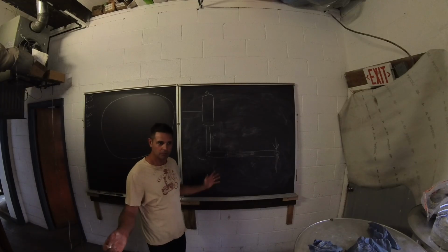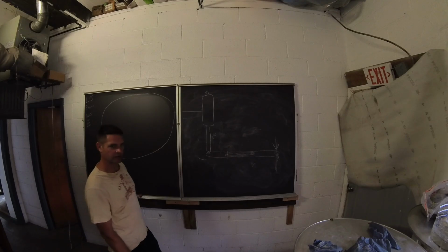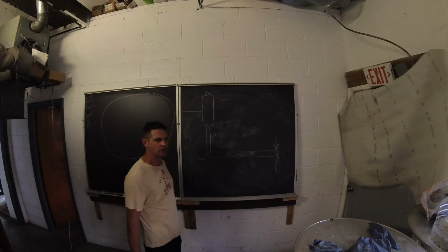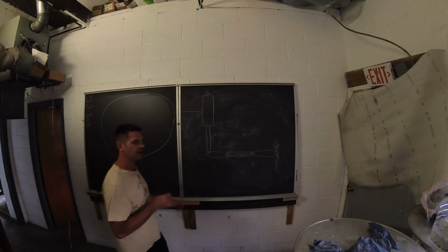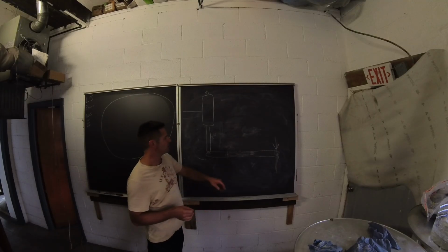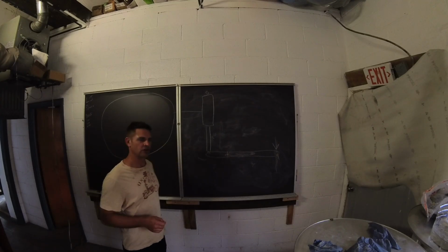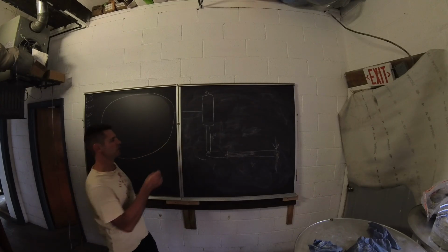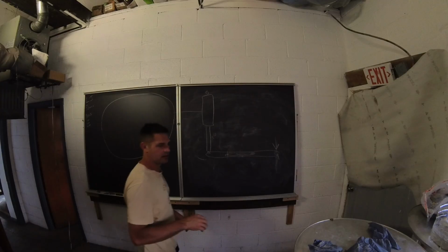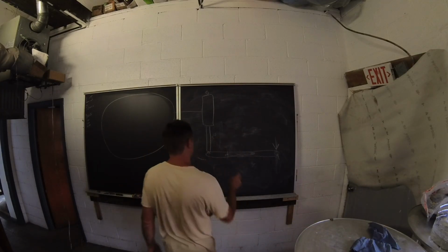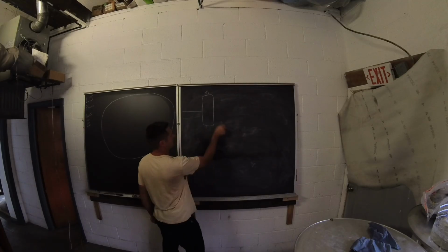Just as an example, but this is the kind of thing that I find interesting, because it's easy to turn damping on and off and close orifices and open valves and go in that direction, but I don't see a lot of people actually changing the spring rates or just the load of the springs. I see very little of that, and I think there's a ton of potential there to play. And it's the kind of thing you can play with without spending a ton of money.